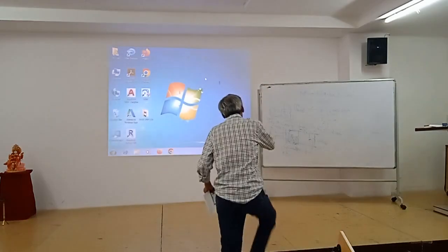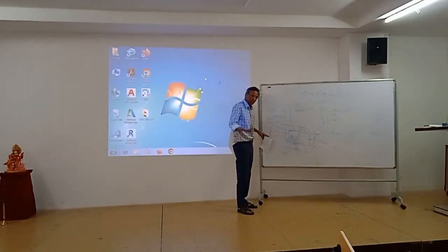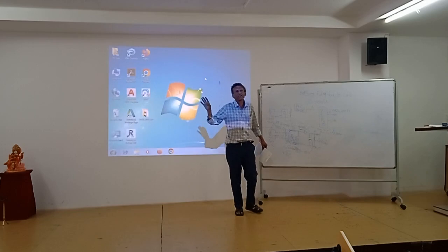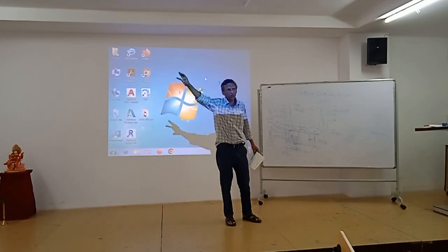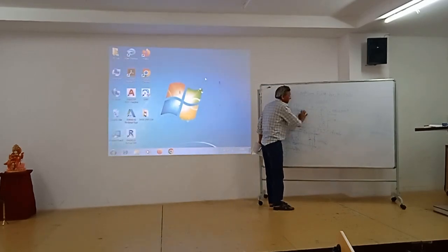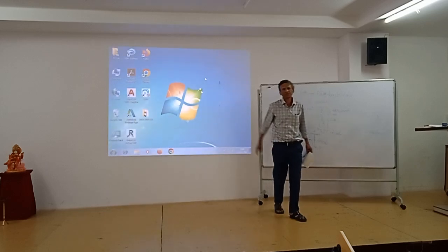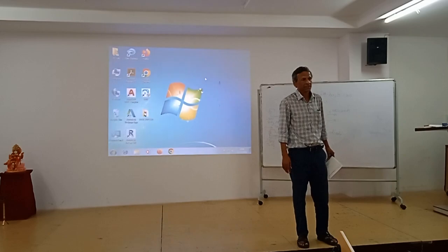So from this perspective, a properly tuned PFC gives THD less than 5% and power factor will be 0.99. So now in every appliance abroad, Europe, Japan, even China, it has come. First stage is PFC. Then you can do whatever you want.